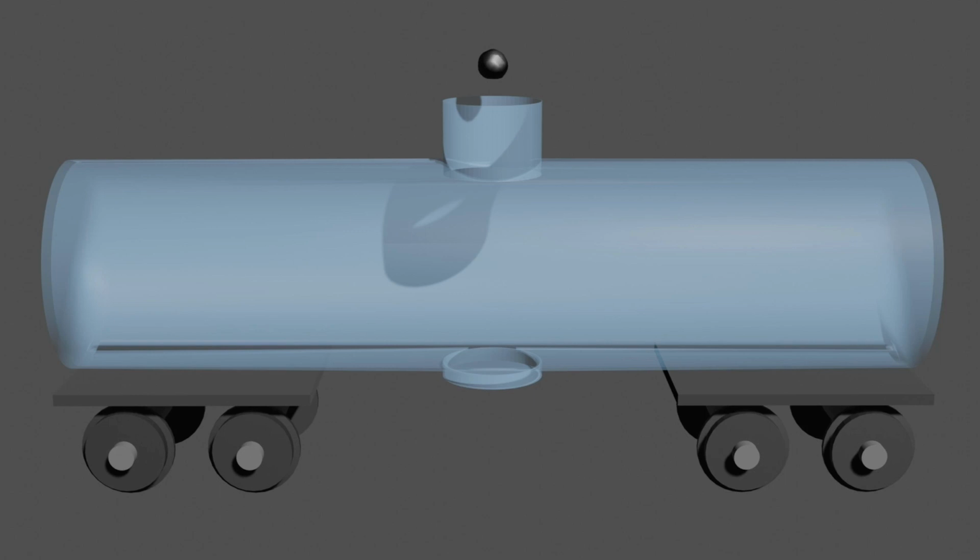The scavenger needs to contact the dissolved H2S, therefore proper mixing is essential. Many assume that the movement of the fluid in transit is often enough to provide mixing energy. However, it is generally not sufficient since baffles are typically in place specifically to limit sloshing.